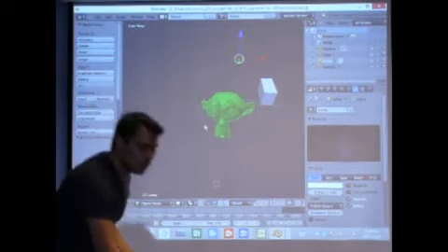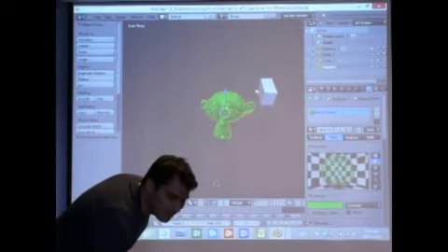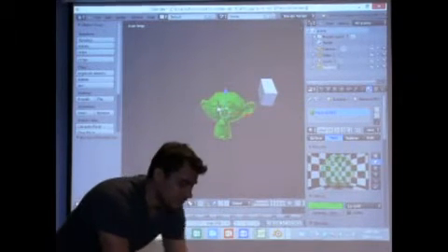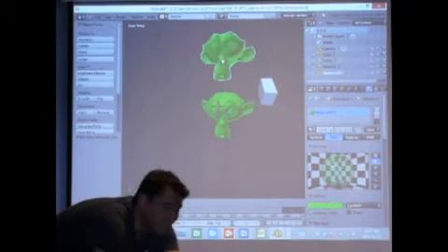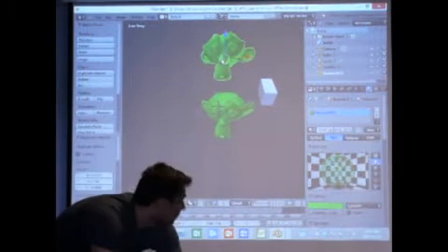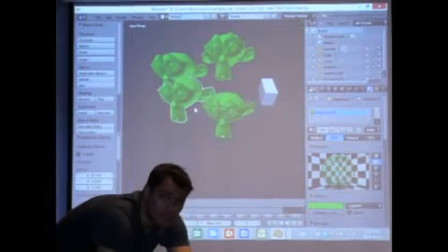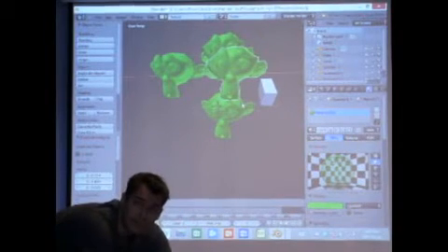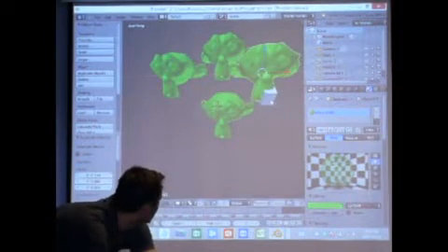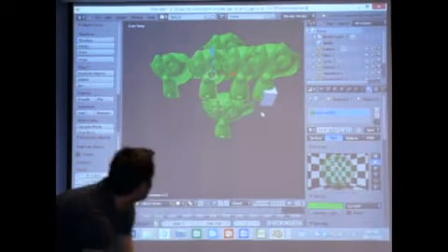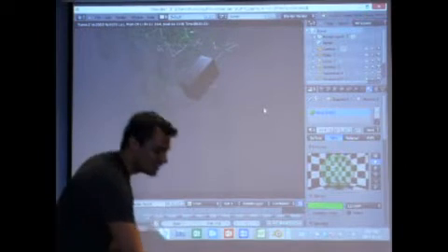I should show you that if you want an object and you want to duplicate it, usually there are many objects the same. You can just press Shift D, and you'll duplicate the object and move it around. You can make tons of them. Keep placing them everywhere. And of course, if you want to place them along a certain axis, you press X after you press Shift D to control where you position them. I'll make a whole bunch of different ones on the X axis. And if you mess it up, press Control Z to get back to where you were.